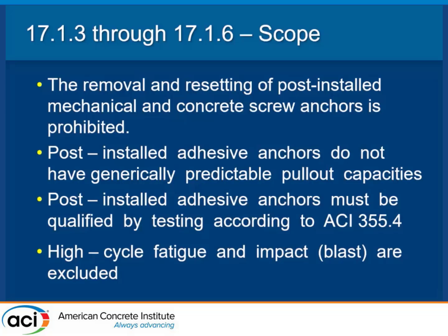So adhesive anchors, post-installed anchors, they're hard to predict. That's why, from just general knowledge, manufacturers make new products all the time, especially when it gets into mechanical anchors. We need them to test, to give you all the capacity or get you all the variables we need. There's no way for us to give you a way to predict a mechanical anchor or a post-installed anchor's capacity without them doing testing. The variability is just too high. We don't cover high cycle fatigue or blast.